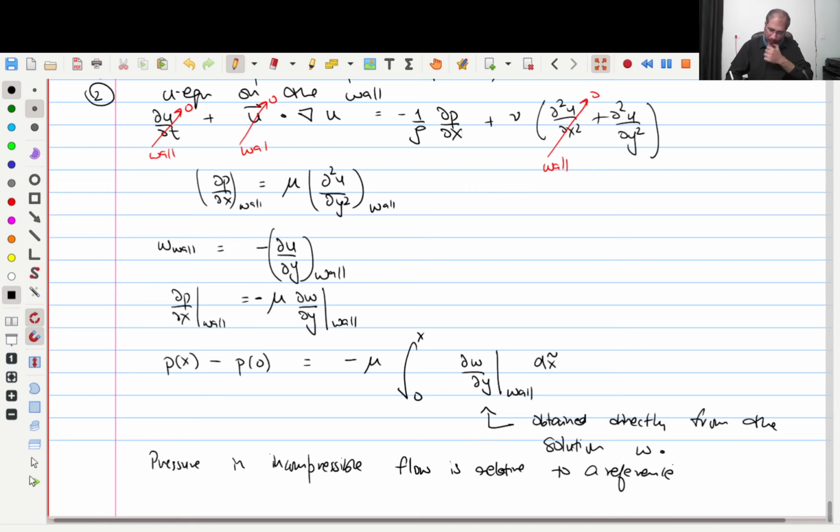So one intuitive reasoning for this is because in the equations of u and v, you have the gradient of pressures. You don't have a pressure term. So it's just the pressure difference values that come into the equation. So there is no reason for the absolute value of pressure to matter in incompressible flows.